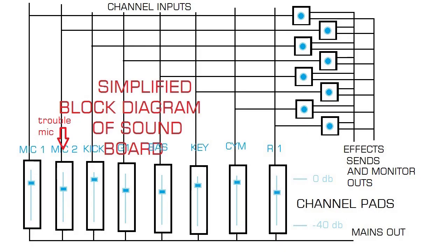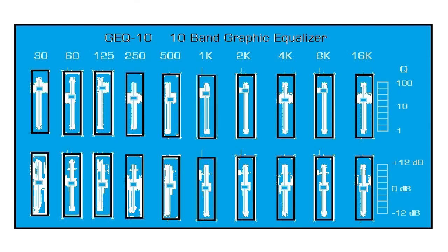Try moving the mic back before doing anything, and remember, dropping the mic back more than a couple of decibels will seriously hurt the sound if it's a main vocals mic. Backup vocals, not so much. For the best of both worlds, use a dedicated EQ on an effects end for the mic channel and run the mains without EQ. That way your dropouts will only occur on the problem channel, the vocals, and the instruments will run clean. I have a 6-channel 120 watt PA built by Custom back in the 60s that has built-in spring reverb and a 6-band EQ just for this. It's a gem.